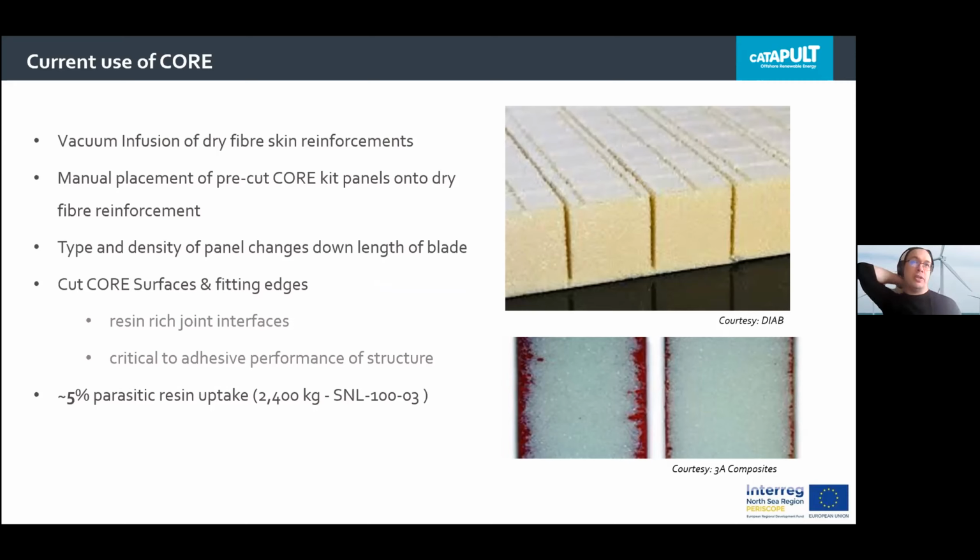Not only are those perforations taken up, but the cut surfaces of the foam, where the individual cells of the foam, as you can see in the bottom right, are taken up with resin from the resin infusion process necessarily.